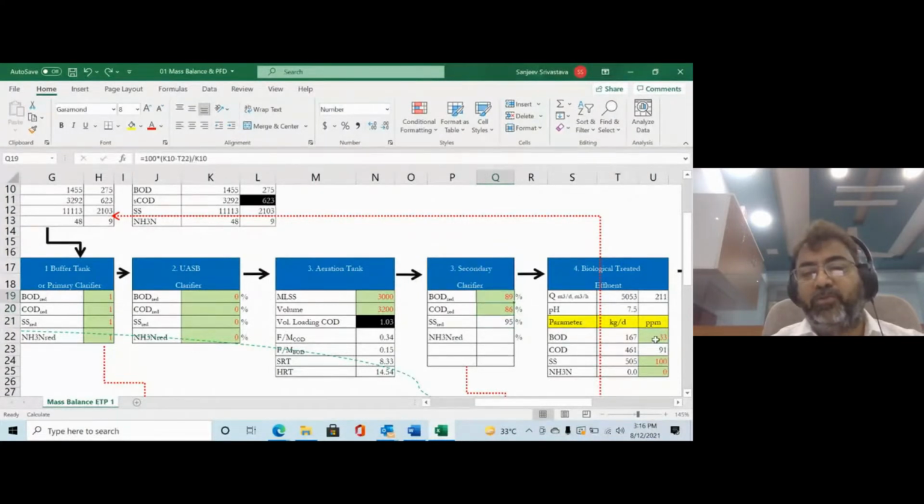And what I'm supposed to put is how much BOD I want. So I'll put the BOD I want is 30. And how much suspended solids I want? I want suspended solids of 25. That may result in 99% SS removal. So I have to design my clarifier system. Will my clarifier system be so efficient that I go for 99%, or I cannot commit suspended solids 25? Because treated water quality is also important.